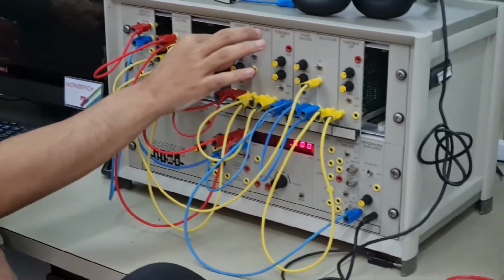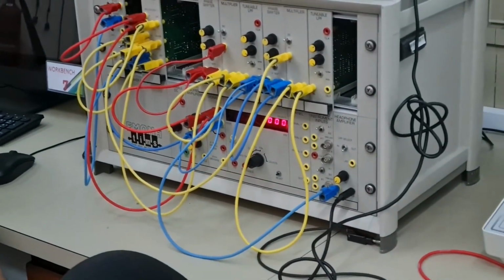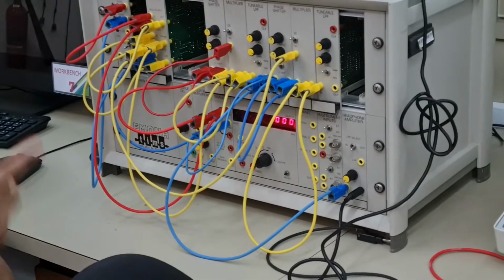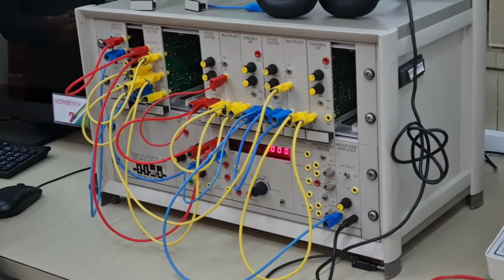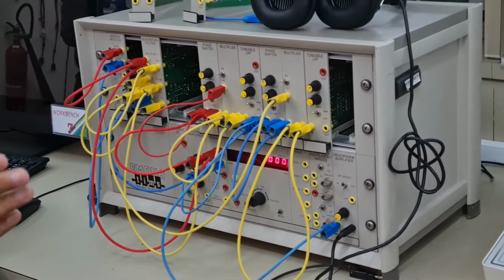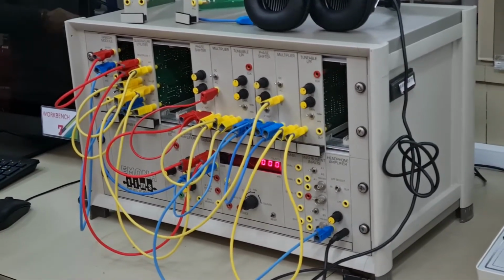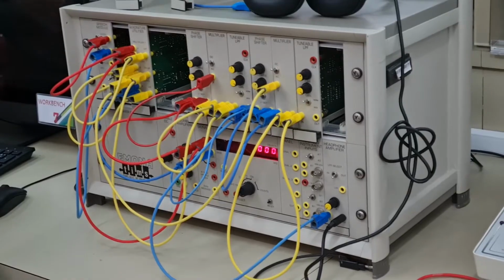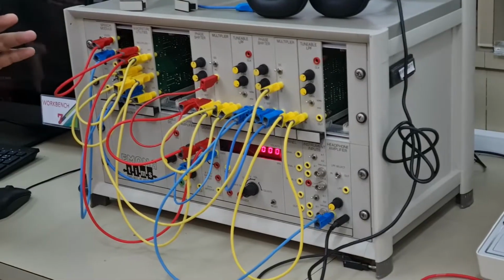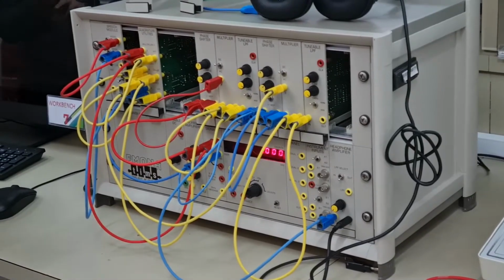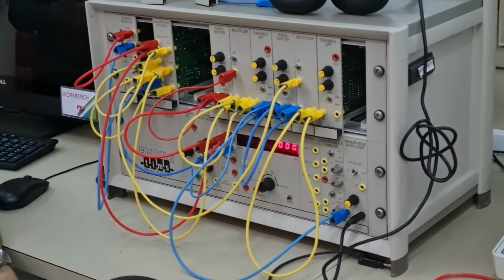Okay, this we can hear from the headphones. How about in digital signals? How can we identify it? So this is why you always have a period for testing. Before you actually start transmitting, you do a test. You transmit a known signal and see if you get the correct signal. If you don't, you think about how to change it. This is what they actually do. They transmit a known signal and receive it. On the receiver side, if they see it's different, based on the difference they know the phase difference, and then they correct it.